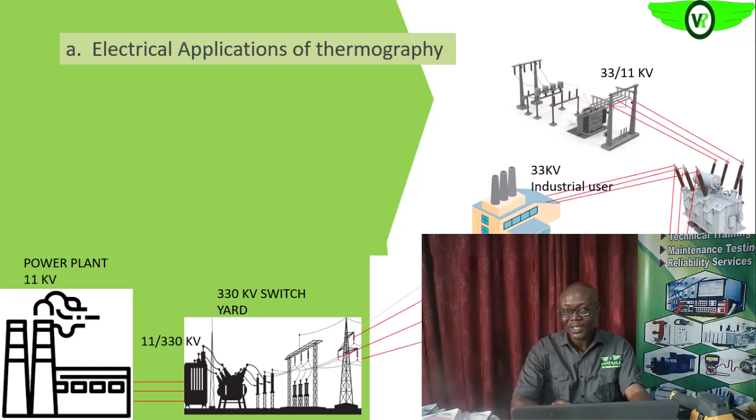So I squared R is increasing at that loose point or loose connection, it means that the heat dissipated at that point will go up. Okay, so overload situations will also generate higher heat than usual. Once you overload an equipment, the current flowing through will go up, so the heat energy that will be dissipated will also do what? Go up.